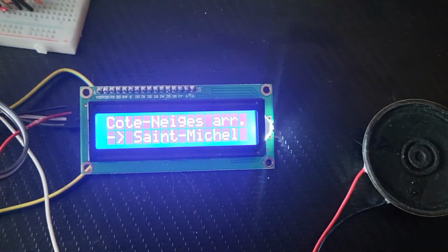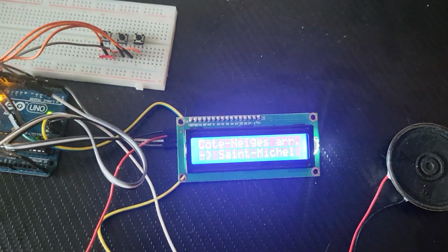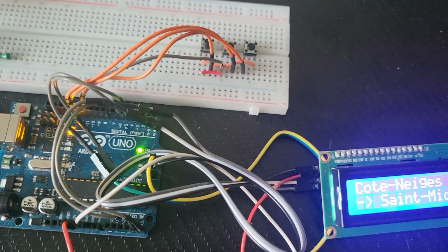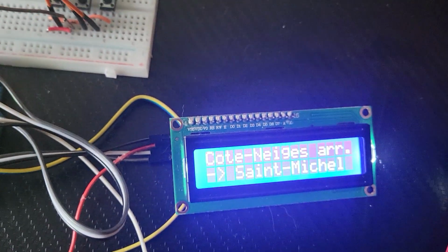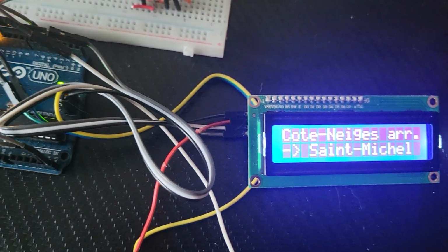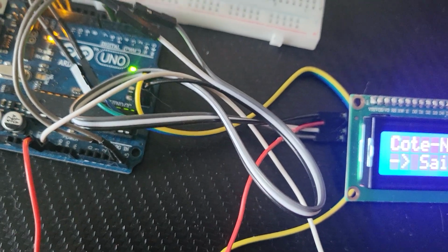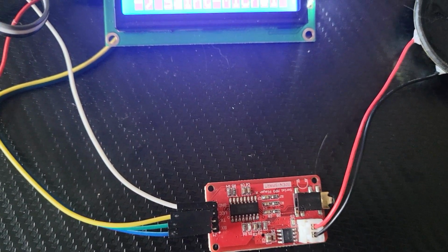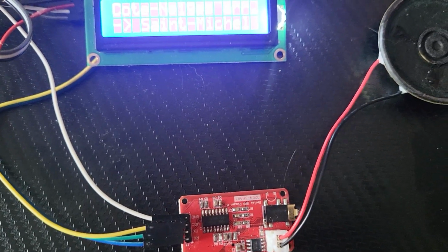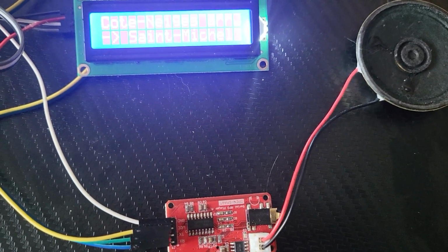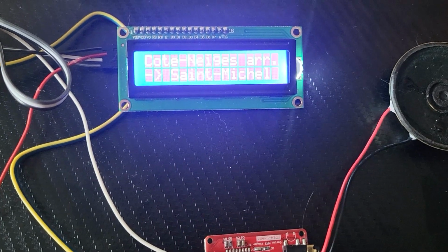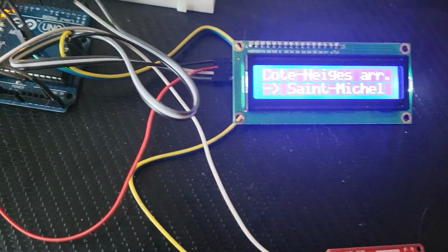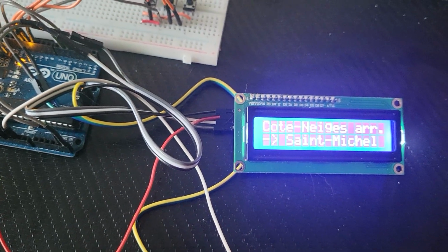And yep, we're just back to the beginning. And this is it. It's just the simple circuit, which I can explain a bit more in detail, because the LCD runs off the I2C protocol, which connects through the analog pins of the Arduino, while the MP3 player itself uses the serial protocol, but it doesn't use the hardware serial pins, which are 0 and 1 on the Arduino, but rather user-defined software serial pins 5 and 6, which is how I've coded it in,